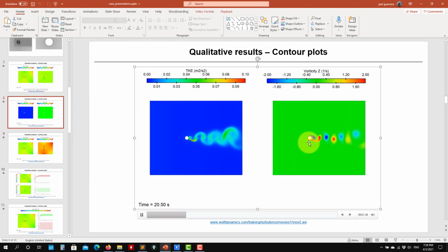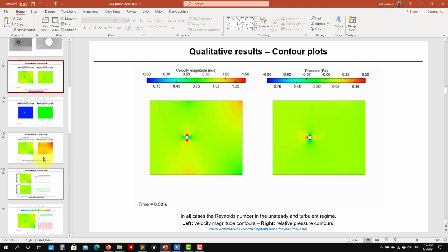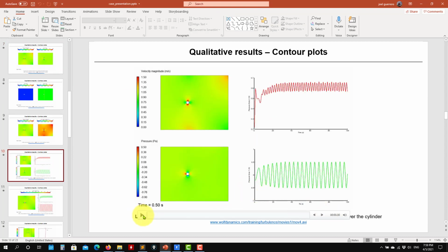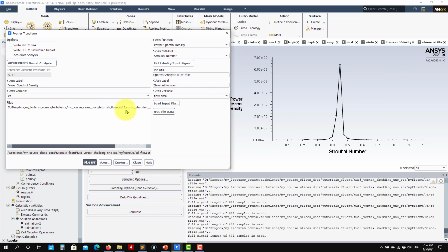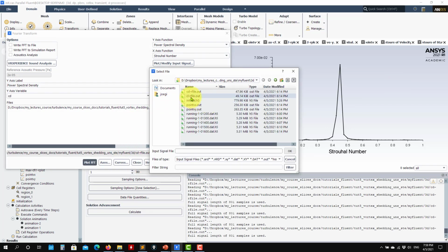See that the shedding, you have a vortex separating from here and here, and from this vortex separation you will see a higher frequency in drag, and the lift frequency will be half of that, due to the vortex shedding that you see here. Those frequencies in this case, see here, this is half of this. So usually we look at the lift frequency, or if you have lateral force, also the lateral force, but the drag frequency will be twice. So now let me move to lift.